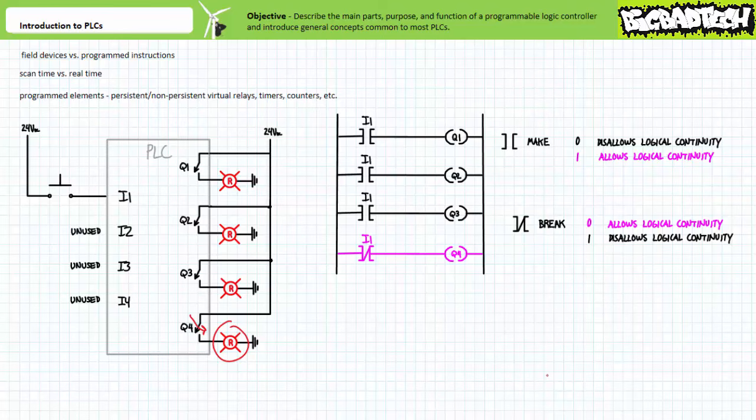This can be used to your advantage to perform powerful functions ordinarily not possible with hardwired relay-based ladder logic, or just as easily, one can impale themselves upon this feature and bleed to death. For example, consider a critical momentary input on line 1 that disappears by the time the CPU returns to the top line. Ordinarily, the CPU executes the scan fast enough not to make this an issue. However, for critical motion control tasks using a lengthy program, this might be a deal breaker. Good efficient programming practices can compensate for these undesirable results.